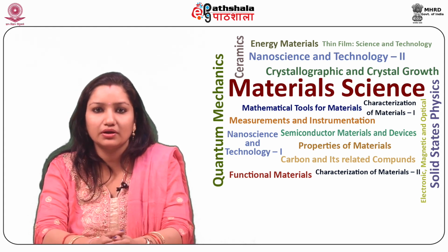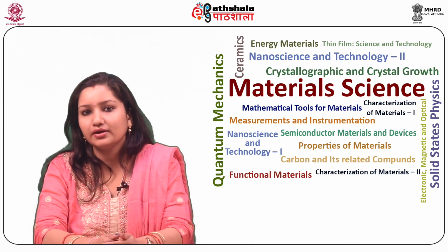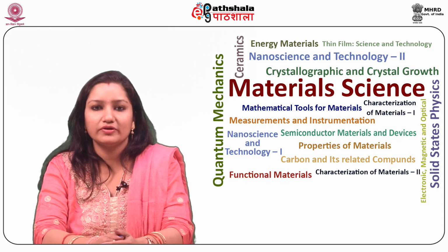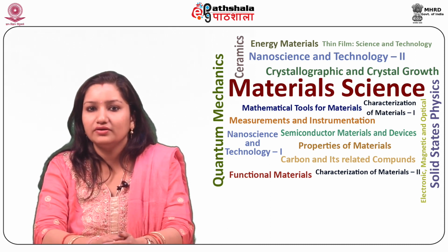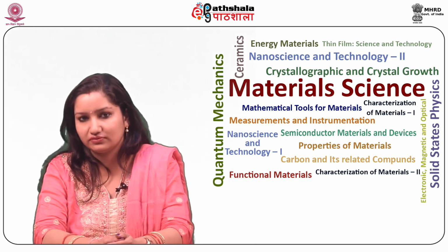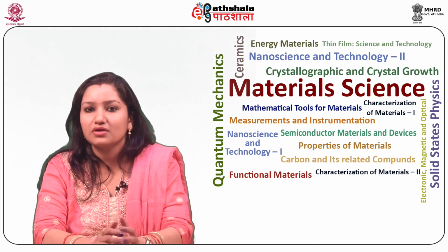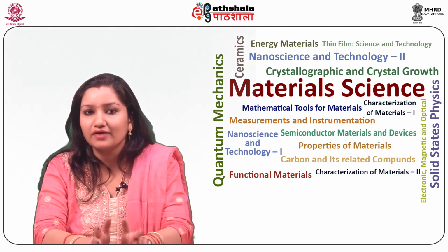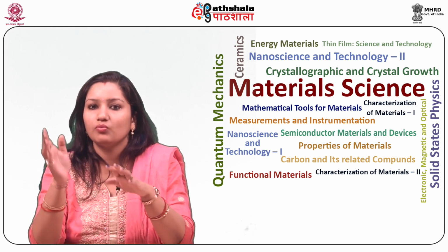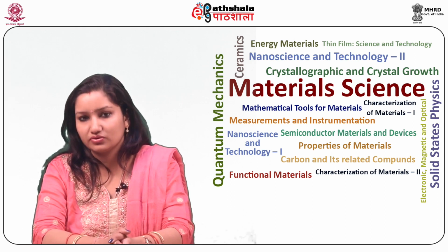The next advantage is that DSSCs work even in low light conditions such as non-direct sunlight and cloudy skies. They are more economical, easy to manufacture, and constructed from abundant and stable resource materials. The mechanical robustness of the DSSC leads indirectly to higher efficiencies at a range of temperatures. Normally, DSSCs are built with just a thin conductive plastic top layer, helping heat to be radiated away more easily and hence operate at low internal temperatures.